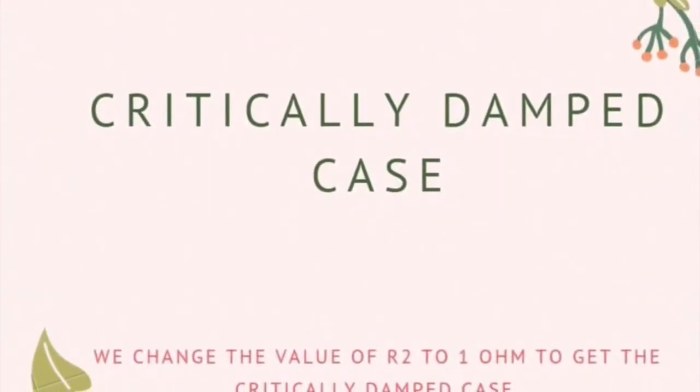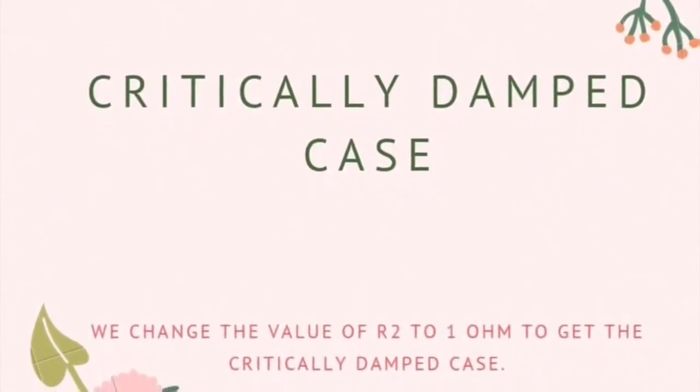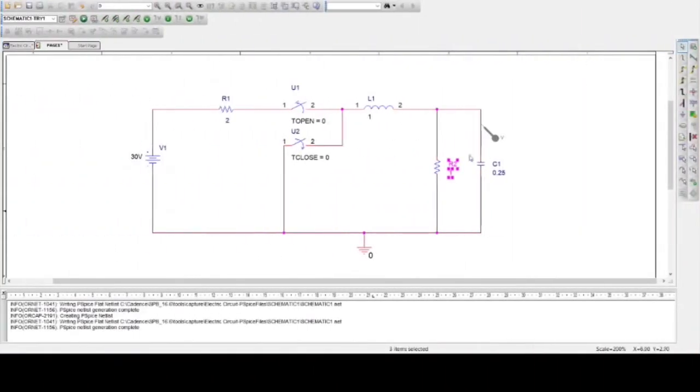For the next case, we change the value of R2 to 1 ohm to get the critically damped case for the natural response. Next, we find the initial conditions by changing the value of R2 to 1 ohm, and we will run the circuit. The initial condition will be shown.